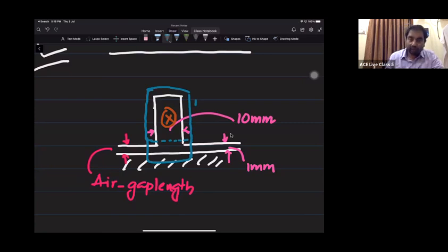Yes. Now let us consider if it has to take the stator path. If it has to take the stator path, what should be the length of air it has to travel along that path? The length of air it has to travel along this path is 10 mm. So without crossing the air gap, it has to complete the path via this way. 10 mm. Then the other possibility is it can cross the air gap.